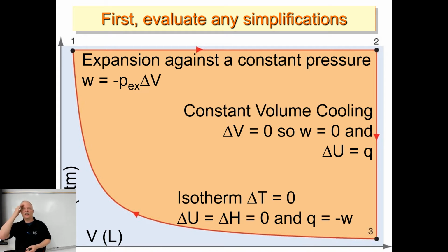And that's, again, looking at the cycle problems, you have to use your common sense, what you know about gases. If I cool things down, the pressure will drop if I'm in a rigid container, constant volume. Number of moles is the same for this problem, 10 moles of helium going around, so we know we're not changing the number of moles. So the only three things that can change are temperature, pressure, and volume. And then that isotherm going up, we know because delta T equals 0 that U and H are 0 and that Q equals minus W. So if we can calculate the work, we just change the sign on that number and it's the heat.